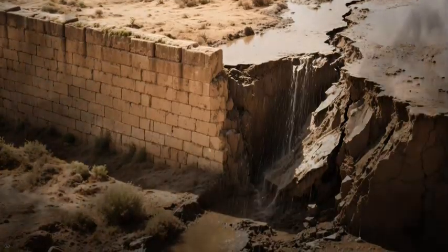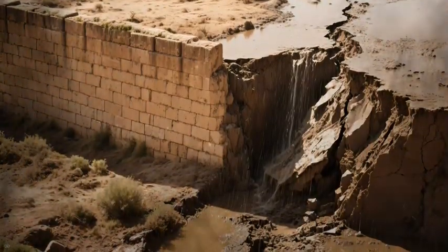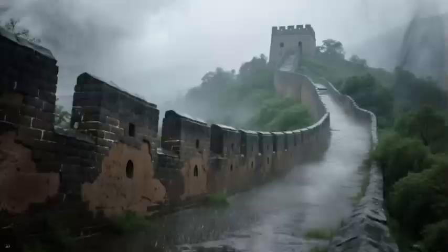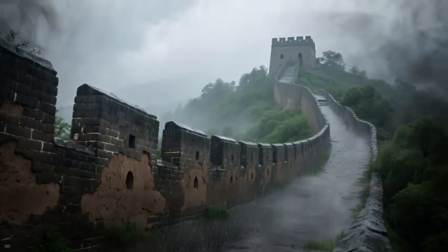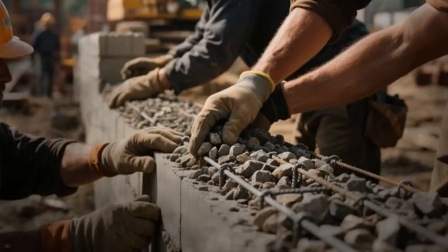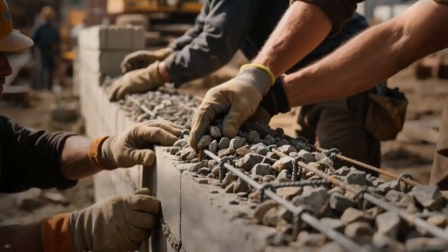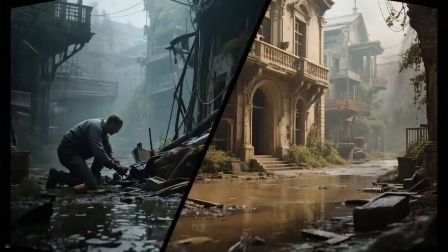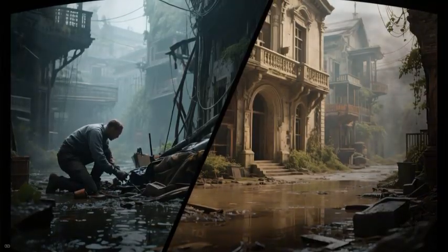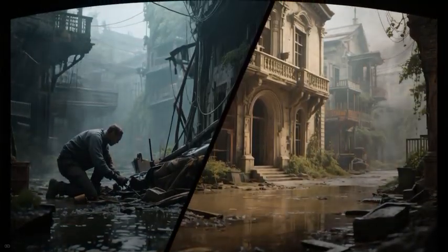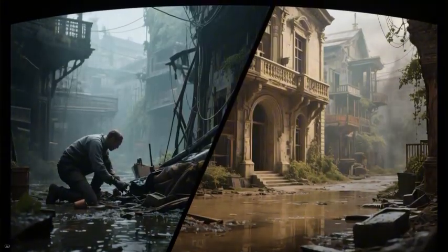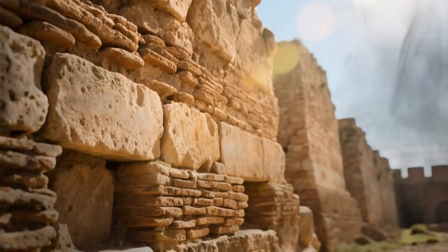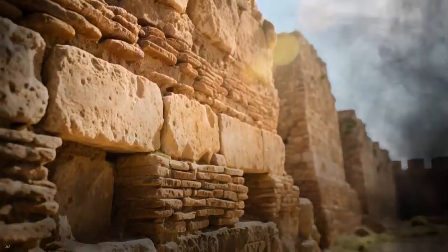Rainfall patterns also shaped construction. In the eastern and central regions, where rainfall was higher, rammed earth walls faced challenges from erosion. Rainwater softened the outer layers of earth walls, gradually wearing them down. Builders tried to reduce this effect by adding gravel layers, reinforcing surfaces, or creating drainage channels. Even with these efforts, sections in wetter climates often needed more frequent repair. In contrast, the arid regions of the northwest preserved rammed earth walls exceptionally well. Dry air and limited rainfall prevented water damage, allowing many ancient layers to remain clearly visible today.